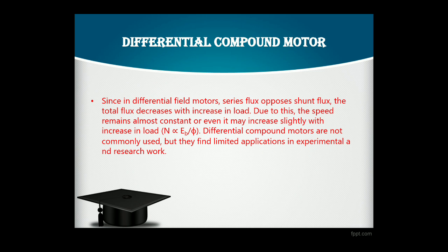Now the next one is the differential compound motor. A differential compound motor is one where the series field flux opposes the shunt field flux. In a cumulative compound motor, the two fluxes are added, that means the series flux aids the shunt flux.